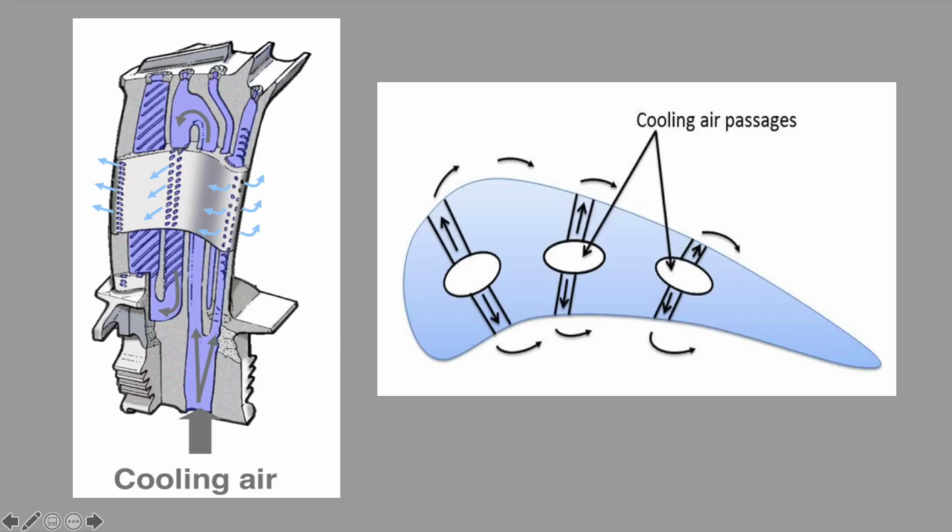The second method is to cool the superalloy. Cool air, albeit at 600 degrees Celsius, is taken from the compressor and passed into the root of the turbine blade, and through a series of intricate internal channels. Channels are serpent-like and wind through the blade to maximize contact surface area. This allows for lots of thermal energy to transfer from the high-temperature superalloy to the cooler air.